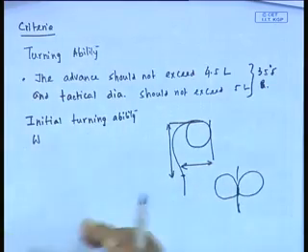Remember that the propeller moves to one side if it is a single propeller. If it is a twin propeller, it will be much less, theoretically zero. But with a single propeller, there is a bias for the flow on one side. So the rudder on this side and the rudder on that side will not perform in the same way. That is why they say that you must do the test on both sides.